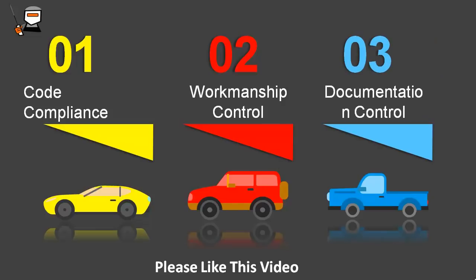The requirement for examination records and inspection reports varies according to the contract and type of fabrication, and there is frequently no requirement for a formal record. When an inspection record is required, it may be necessary to show that items have been checked at the specified stages and have satisfied the acceptance criteria. The form of this record will vary: possibly a signature against an activity on an inspection checklist or quality plan, or it may be an individual inspection report for each item.